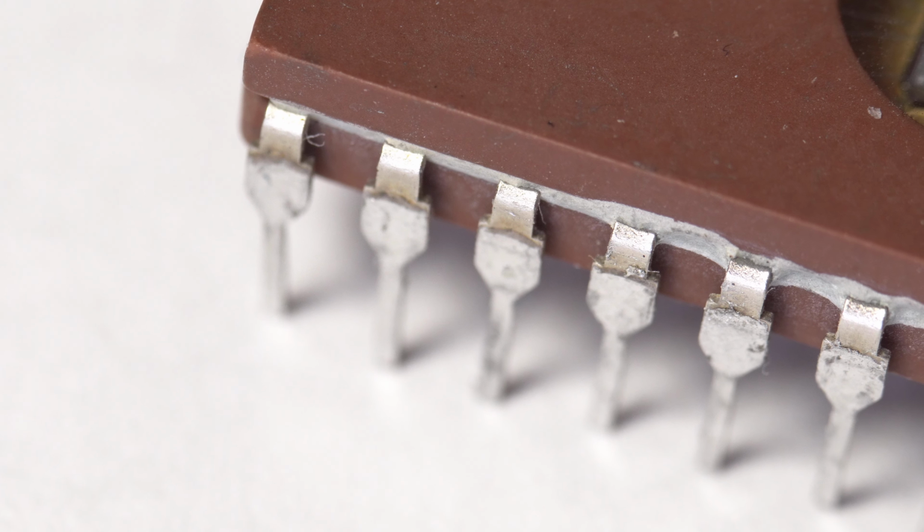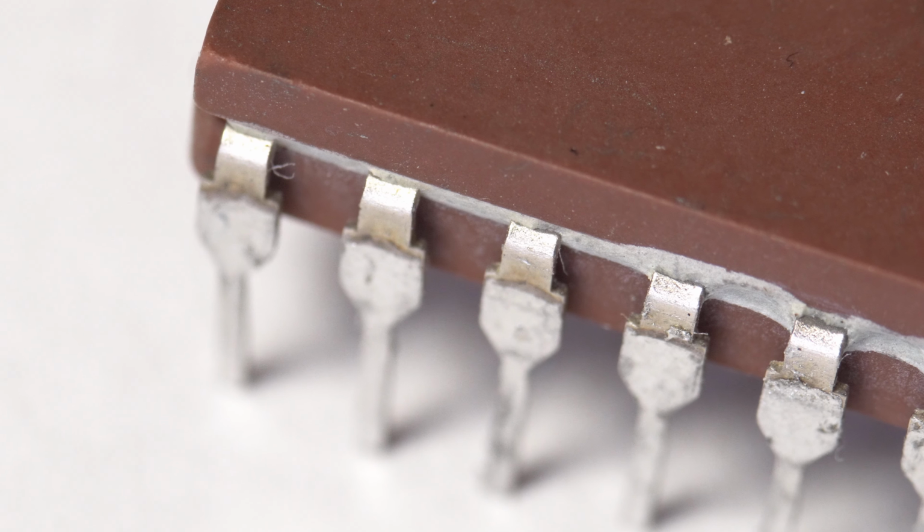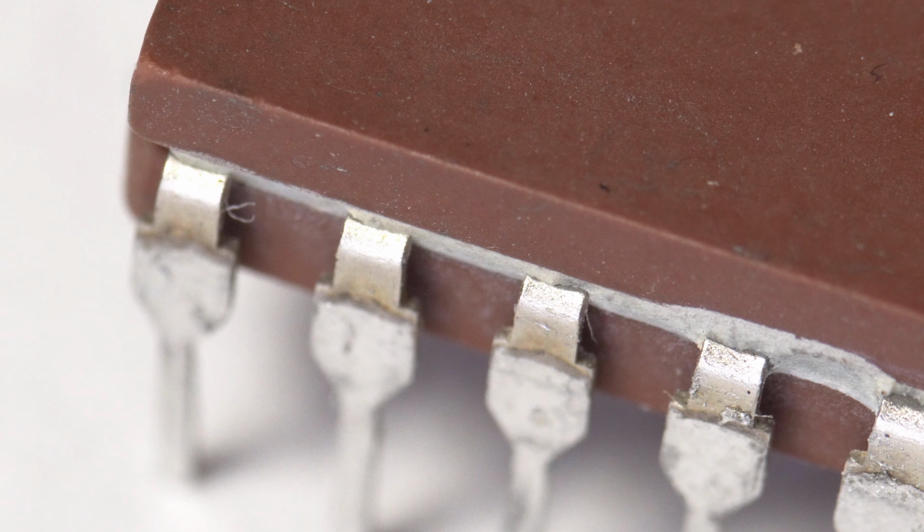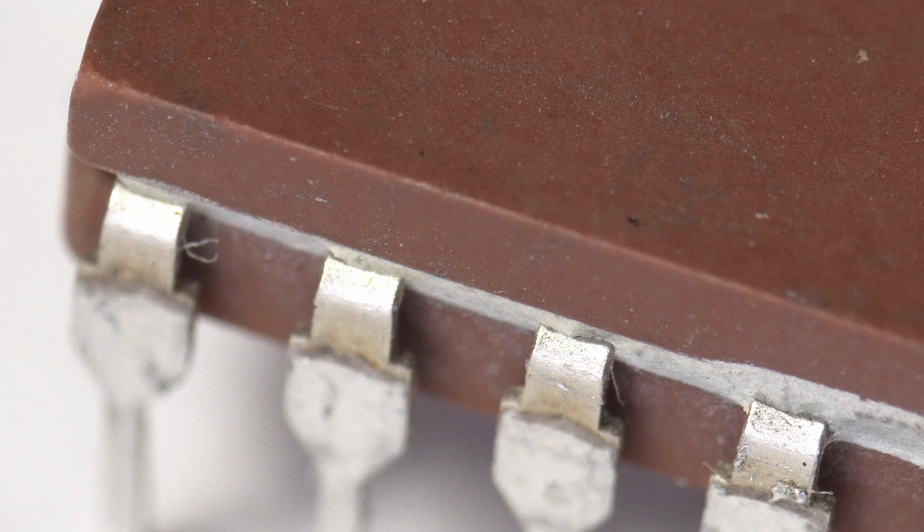Even the chip's own packaging material can become a problem. Starting in the late 1970s, chip manufacturers became aware of trace amounts of radioactive particles that were embedded in the ceramic packaging. This trace amount of radioactivity was only noticed after an investigation of unexplained bit flips that were experienced by the chips. It's also worth noting that even benign things in the environment, such as the radiation shielding itself, could itself be a source of radioactive particles.